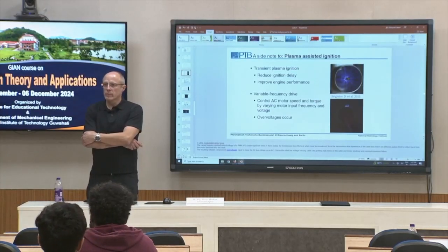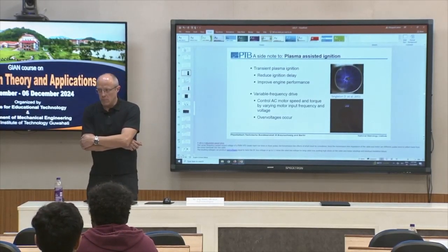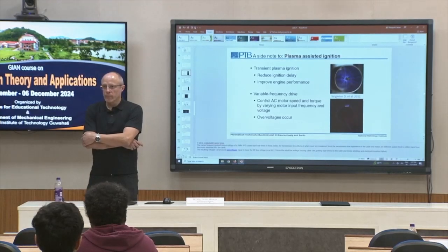So this way we have done the analysis, but we cannot separate the pressure data, which pressure rise is because of the change in cylinder volume and which is because of combustion. Why not? When you use, for example, nitrogen or pure air in your system, you can see the change in pressure due to compression.